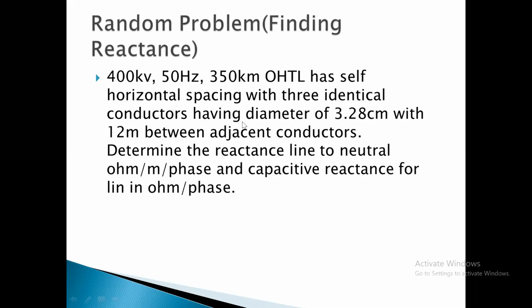So if you know how to find capacitive reactance, you will also know how to find inductive reactance, and then we will add both of these, and we will get the total reactance of the line. If you get the total reactance of the line, you will get the impedance of the line.